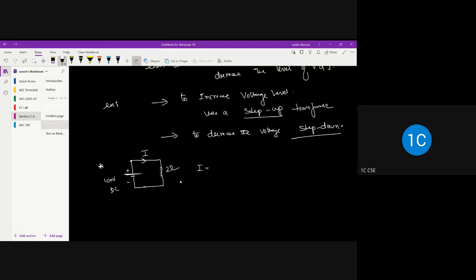2 ohm resistance. And let's say the inductance, because this is a coil, will be somewhere about 2 Henry. But in a DC system, the reactance offered by this particular inductor is 0 ohm because the frequency is 0. So F is 0, reactance is 0, and your current is basically I is equal to V by R. And how much is it? 50 amperes.